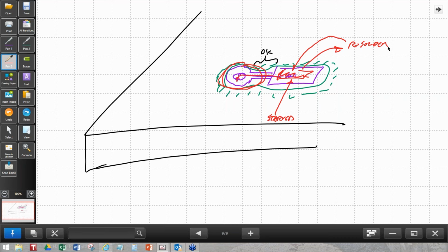Again, think about it when you design that. Make sure there is no path that the solder paste can get off the pad. One way to do that is to look at the actual outputs. I prefer to do it in Gerbers, but if you line it up, you can say, here are the solder mask outlines, here are the pad outlines, and you can look at them and say, is every one completely surrounded or not? Also, if you set it up carefully, most PCB design tools can have some mechanisms for warning you of that, but not all do. So depending on which tool you're using, you need to be cognizant of it.